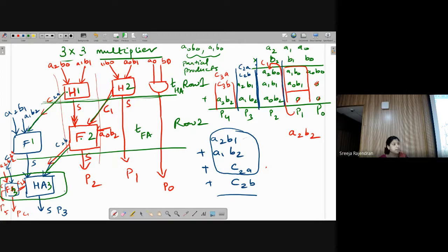Here, when I come, this becomes a ripple carry adder, because there is a serial connection from this to this. So here I have to take all the component bits. In the final stage alone, you have to consider the delay of every connected component, because they do not work simultaneously. It works in a serial fashion here. And here I will have the delay of the half adder plus the delay of the full adder. That is what I have already mentioned as propagation delay, the critical path delay in your multiplier. You have written it. I was just clarifying it a little more.